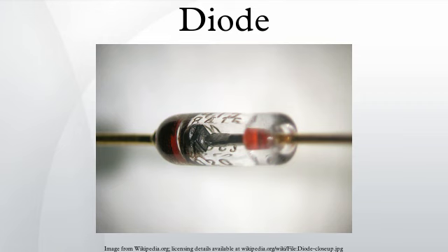Pro-Electron. The European Pro-Electron coding system for active components was introduced in 1966 and comprises 2 letters followed by the part code. The first letter represents the semiconductor material used for the component and the second letter represents the general function of the part, for example, AA series germanium low-power signal diodes, BA series silicon low-power signal diodes, BY series silicon rectifier diodes, BZ series silicon Zener diodes.